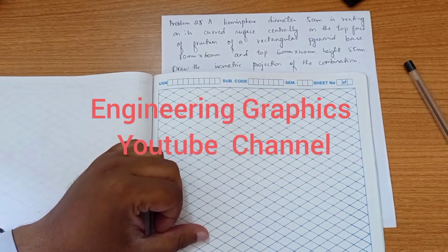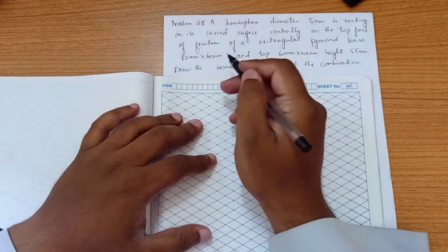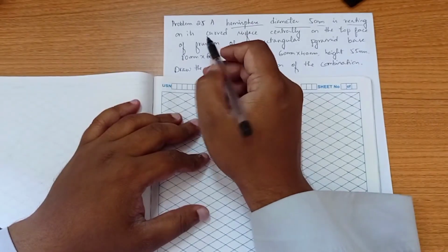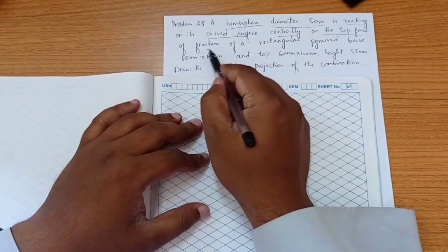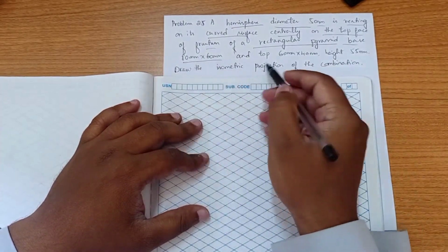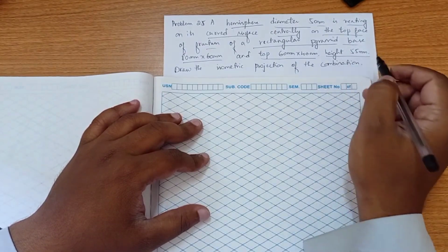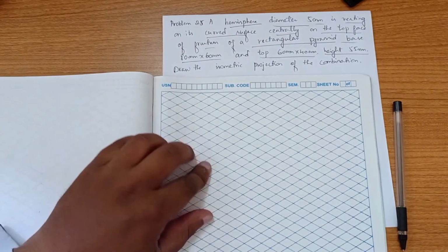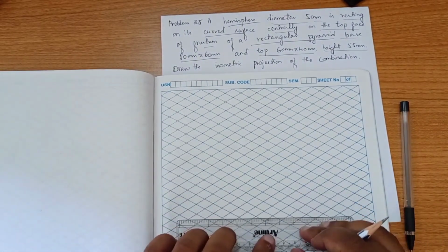Problem number 25 from CAT solution book. So it is a problem from isometric projection. A hemisphere of diameter 50 mm resting on its curved surface centrally on the top face of a frustum of a rectangular pyramid of base side 80 into 60 and top of 60 into 40, with the height given 55. So first we have to construct a frustum of a rectangular pyramid.